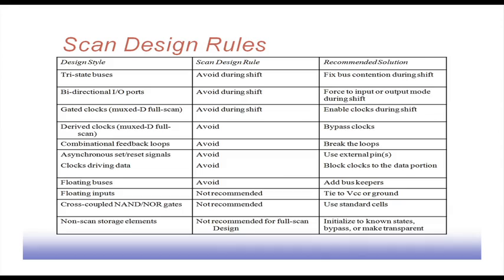So, we have to fix this bus contention during shift. We have to ensure that there is no bus contention occurring during the shift operation. Similarly, for bidirectional input output ports, we have to force the input or output mode during shift. Somehow, we have to ensure that they become unidirectional. So, there are many issues that need to be corrected in the scan design process. And as I have already said, these CAD tools are available which will do these things.